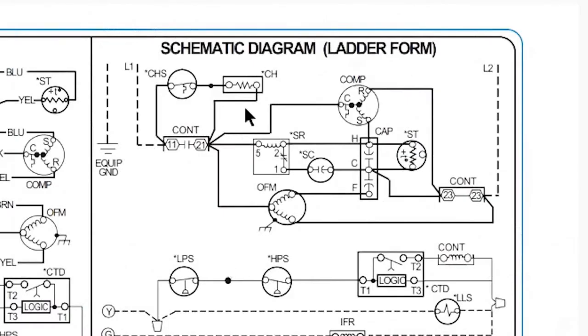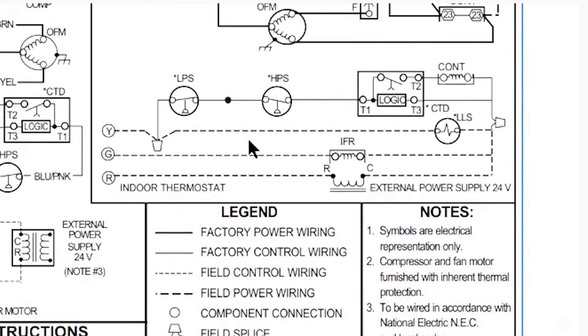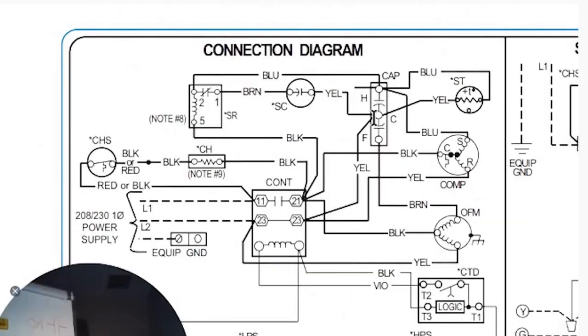The biggest things to know are these symbols have meanings. Every symbol has a meaning, and it will help you understand how the system is operating. You can even catch some manufacturer mistakes sometimes. So hopefully that helps. Connection diagram, everything is shown in more like the position that it is, and in a more complicated system, it's very helpful to locate a component inside of the unit, but the schematic diagram for diagnosis and tracing out a circuit is really the way to go.